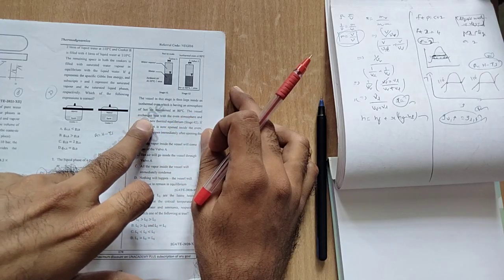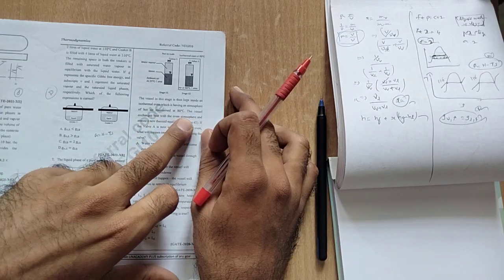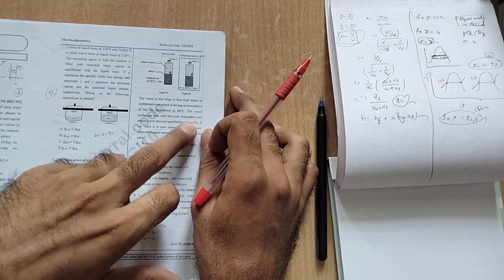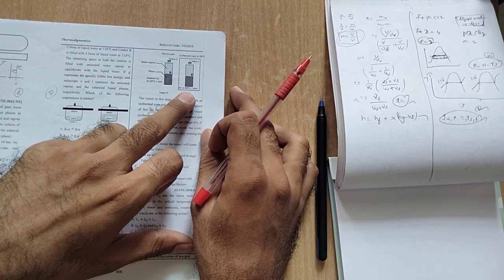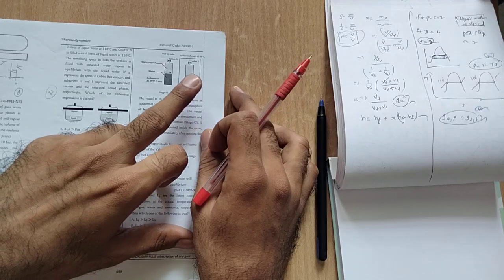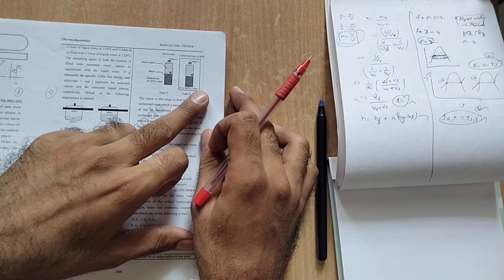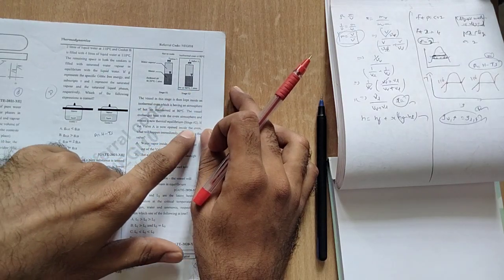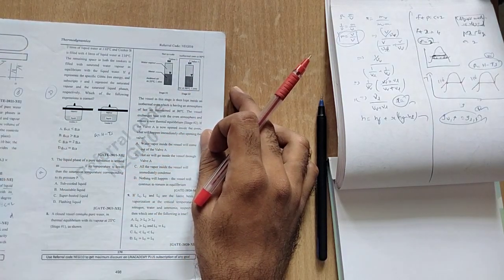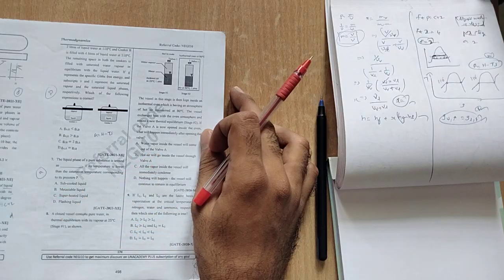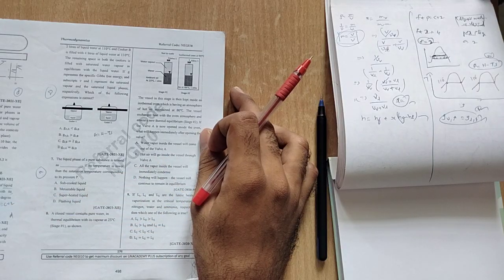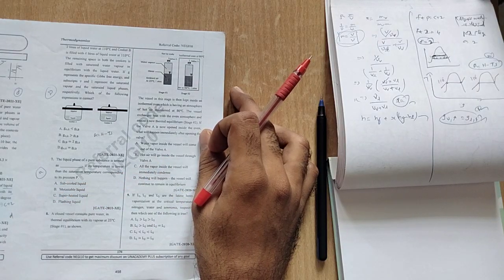The vessel exchanges heat with the open atmosphere and attains a new thermal equilibrium at stage 2. Now a thermal equilibrium has been attained, so inside is 80 degrees Celsius and outside is also 80 degrees Celsius. So what might be the temperature? The valve is opened from inside, so what will happen after opening? Water vapor inside the vessel will come out, so hot air will go inside the vessel, and all the vapor inside will immediately condense now.